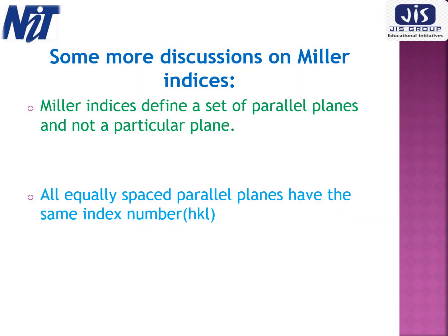Let us discuss Miller indices in some more detail. Any plane parallel to one of the coordinate axes has an intercept of infinity and index 0 for that axis. Miller indices define a set of parallel planes and not a particular plane. This is always to be kept in mind, that it defines a set of parallel planes, never a particular plane.